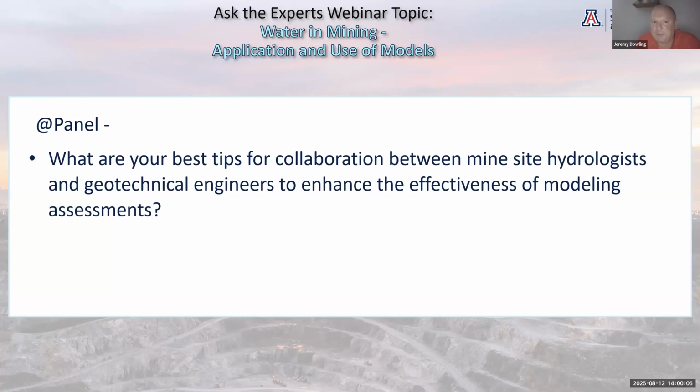And that can then be used to create an empirical calibration of the slope behavior and its sensitivity to pore pressure. So I think just having very integrated slope monitoring data is a really important way to integrate the hydro and the geotech to get more value out of both, and ensure it's all aligned in understanding the slope and how to manage it.